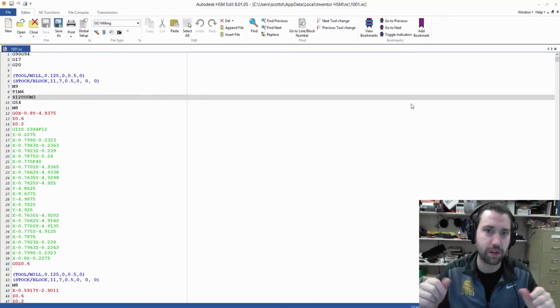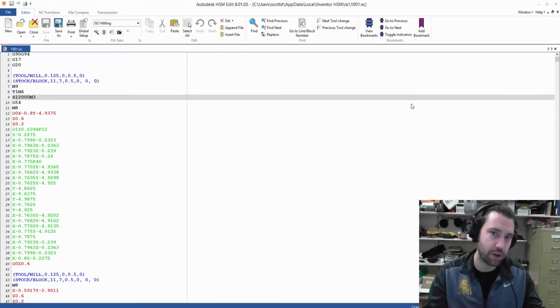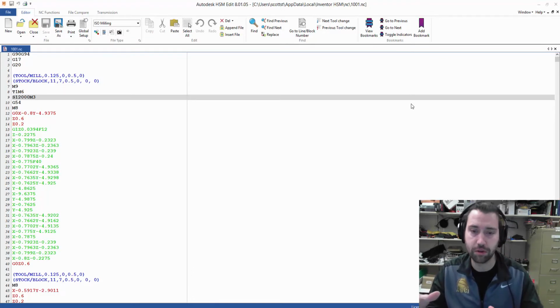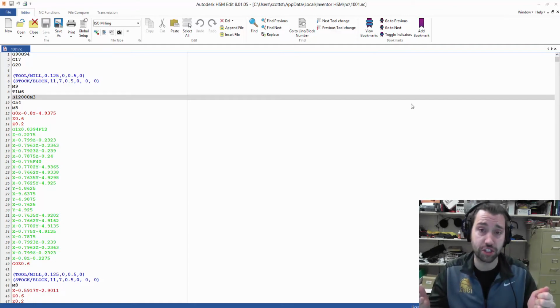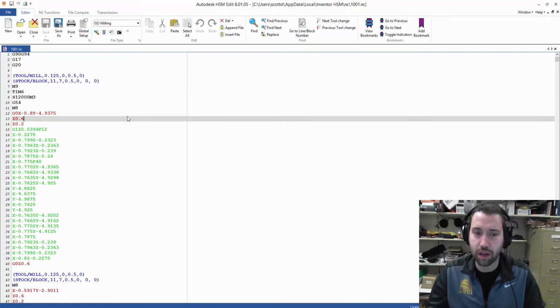Once we've created a piece that we're ready to cut on the CNC router, we're done with the CAD side of things, and we're ready to move into the CAM. That's the computer assisted manufacturing. And this is where we create the set of instructions that whatever device is going to help us manufacture the part will make it. In the case of this particular assignment, we're interested in using the CNC router, and those typically use a file type called G-code.